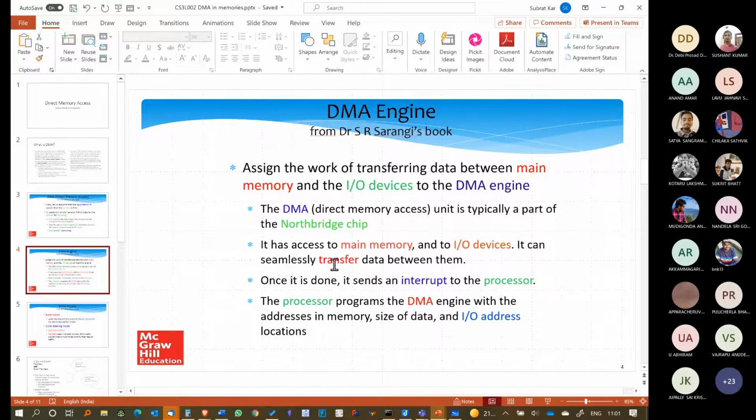So can you please give me the bus? Because data needs the bus. I and that IO device are now going to talk for the amount of time it takes for me to transfer 25 mega registers into that device. So please let me have the data bus and the address bus for that amount of time. I will put the address, I will increment or decrement the address as you have programmed me, and I will make sure the data is received by the device. You don't have to come into the picture. Fine.